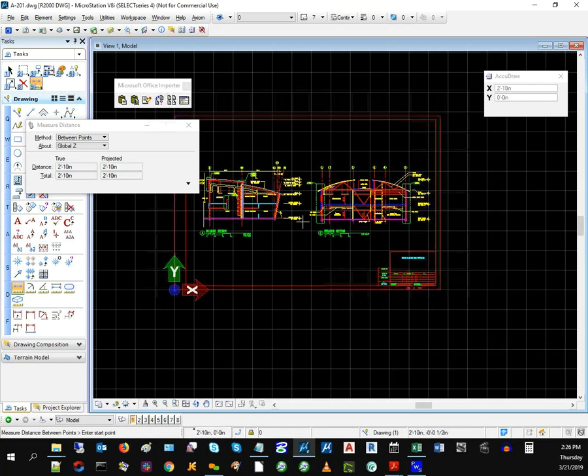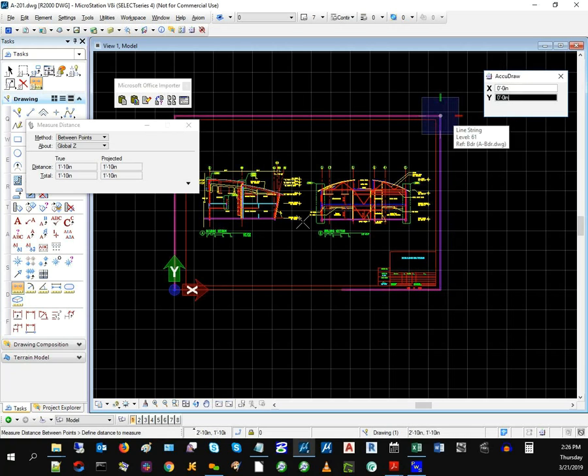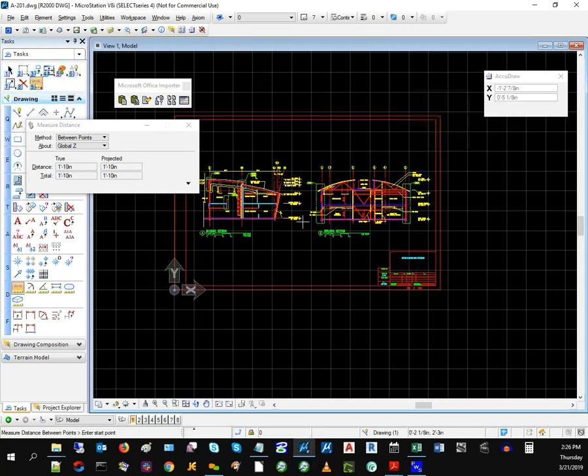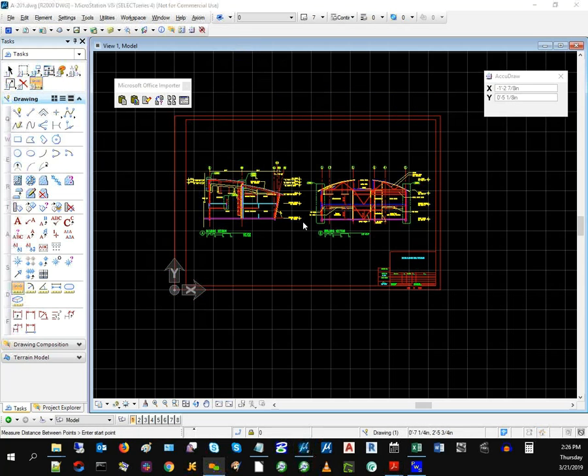So that tells me that at least as far as opening it in MicroStation, the way I did, the units are coming out as something that I would expect. And so here you see it's 22, so it's 34 by 22, which I think is C. Now we'll go from here, we'll look at the levels, because this is something that later we're going to have to map.